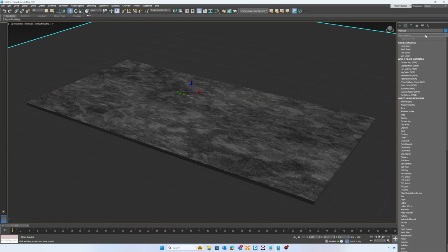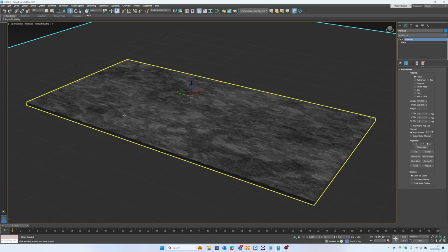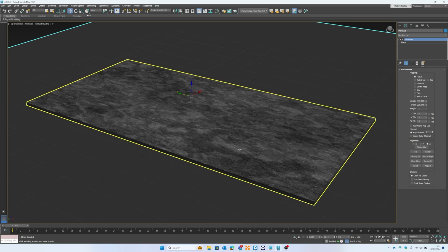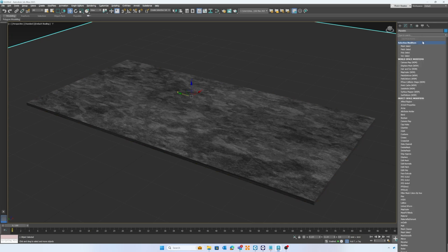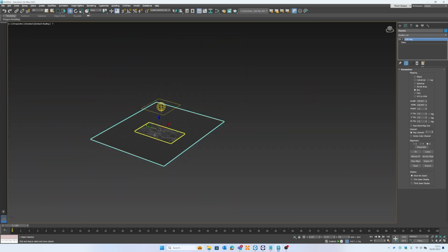So we use a modifier against our components called UVW map. And with UVW map, so long as it's something fairly standard shaped, like a cylinder, a plane, a box, or a face, we can control with UVW map how that will work. If you've got something that's very aesthetically curved, you'll need to use unwrap to first unwrap that surface so that you can get the flat, put the texture on it in its flat form, and then wrap it back up.